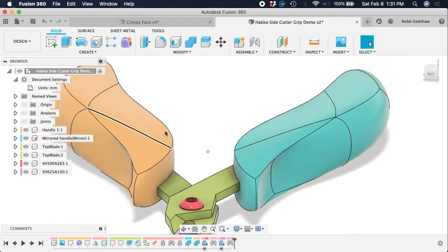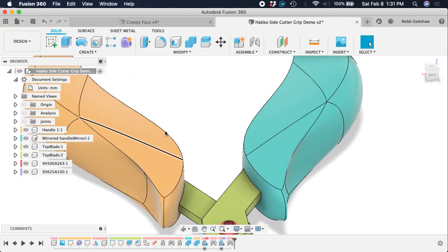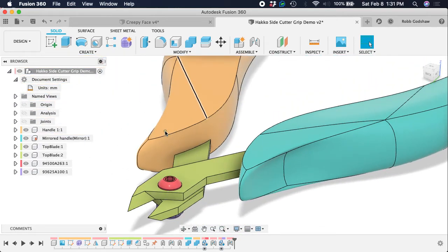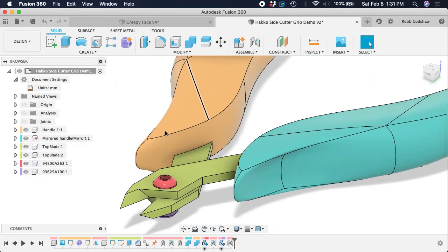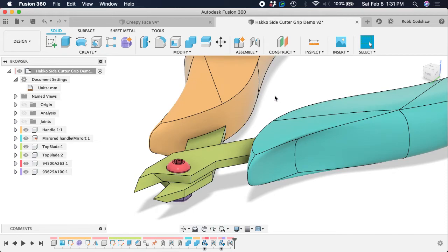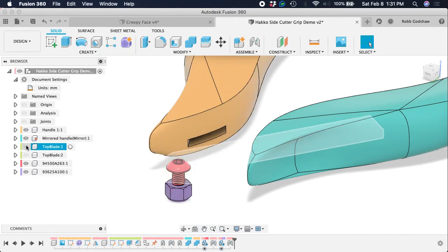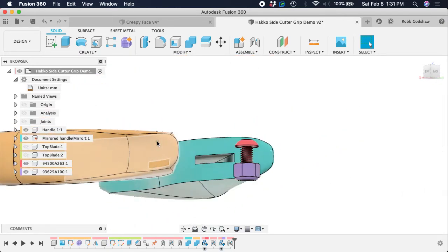What I don't think is going to be okay is I don't think that this is going to fit together. Because 3D printers tend to make holes too small and objects too large just by a little bit. And if my dimensions are accurate, there's just no way I'm going to be able to fit this 8 millimeter by 2 millimeter piece of plexiglass into a hole of the exact same size in a piece of PLA. So there's a couple ways of doing that. We could either shrink these down before we cut them, or we could enlarge the holes.